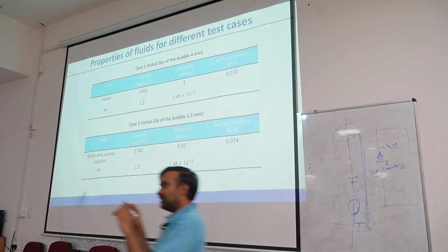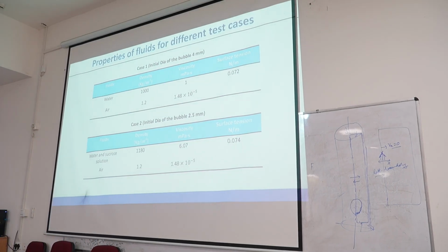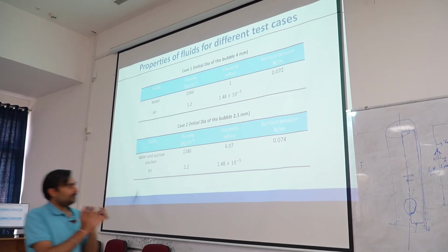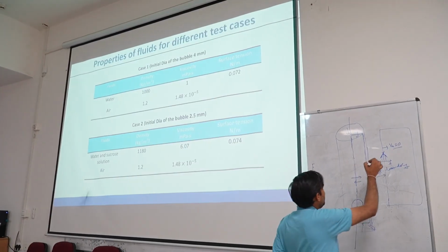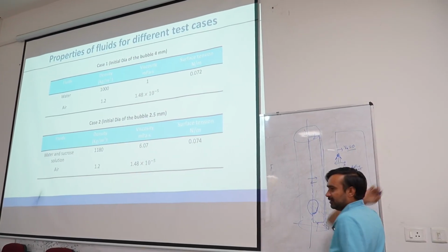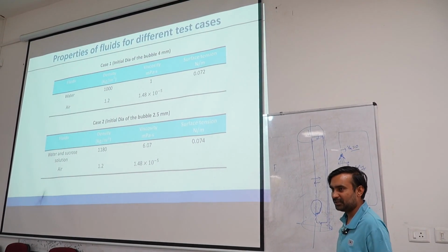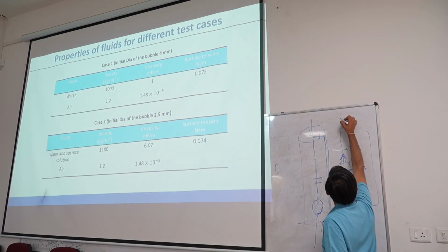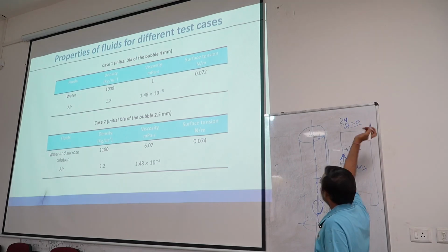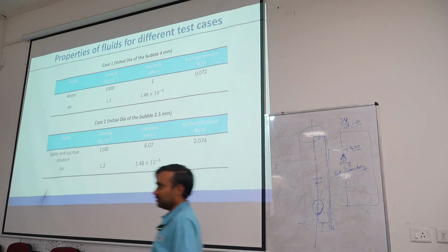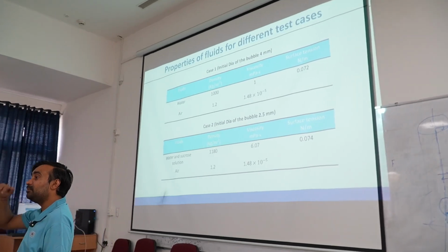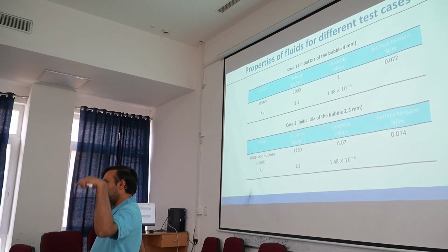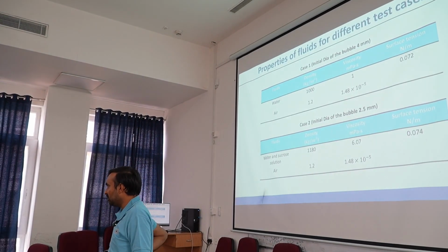So, it means the gradient of the velocity field will be symmetric about this particular point. So, if it is symmetric about this point, I can say that the gradient of my tangential velocity has to be equal to 0, because the profile will be symmetric. So, because of the symmetric profile, this gradient will be equal to 0.